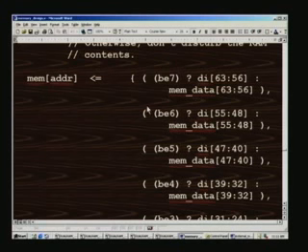In 8 clock pulses you would have written 64 bytes, whereas in DCT it will take 64 clock pulses to process. So that means the writing time is very high, and this may have to be done from the video grabber, which means you have lots of time for the video grabber, because processing is going to take quite some time.